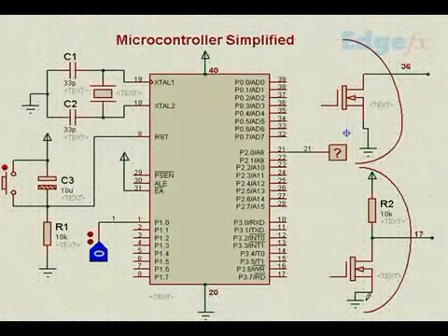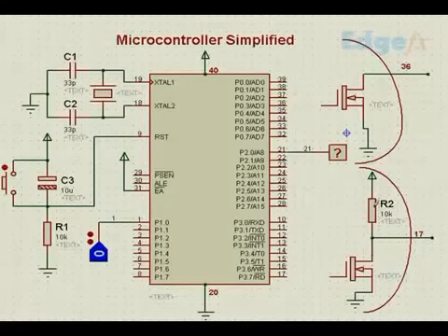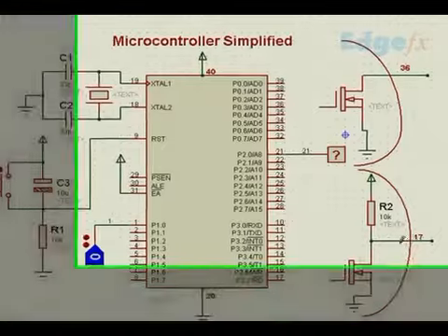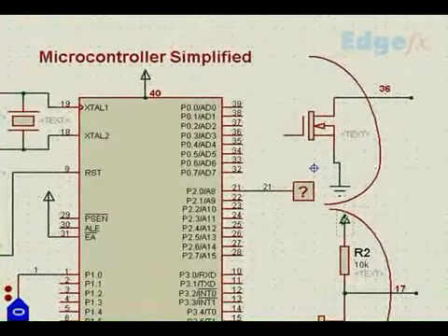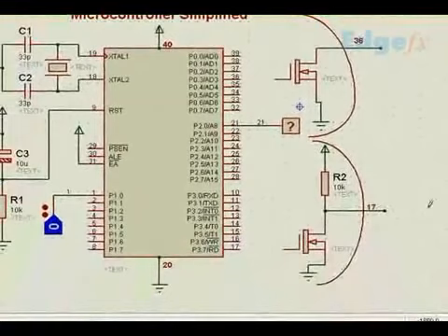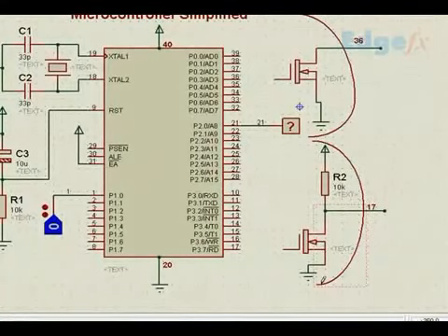You see, this is inside the microcontroller. This is internally pulled up. Pulled up means there is a resistor which is connected to positive. Our electronics friends call it pulled up. I don't know where they pull it up. Anyway, this is called pulled up. That means this particular pin, pin number 17, can source. Source means current can flow this way. When this is switched off, the current can flow this way. If it is switched on, the current can flow this way.